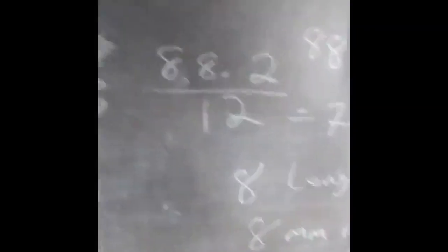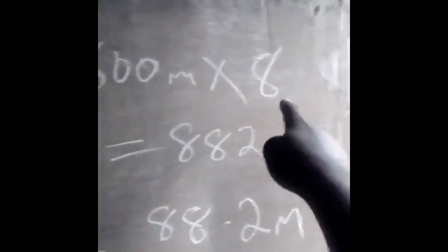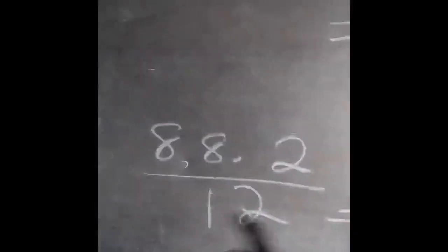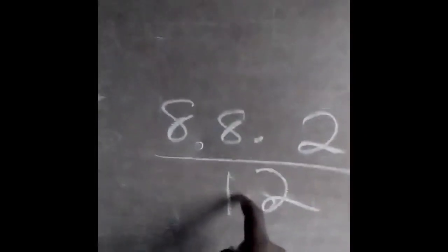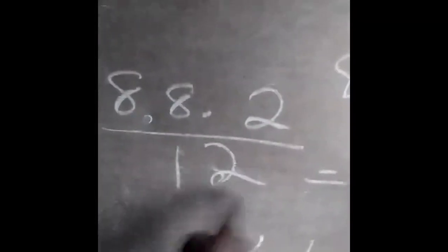Nothing else. You know how we did it. Calculate the cutting length of the stirrup. Multiply it by the number of stirrups required, and by the total number of pillars in the building. Then calculate everything in meters and divide by the length of one rod.